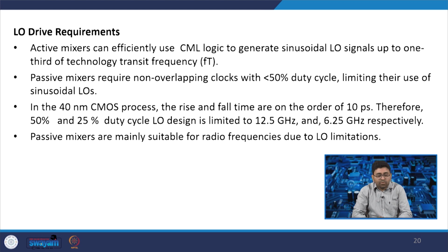Now for the LO driving requirement, the active mixer can effectively use CML logic. In both configurations that we have seen, the current mode mixer and the voltage mode mixer, the LO requirement is a 25% duty cycle. If we compare this passive mixer with the active mixer, the active mixer can efficiently use CML logic to generate the sinusoidal LO signal up to one third of the technology transit frequency.